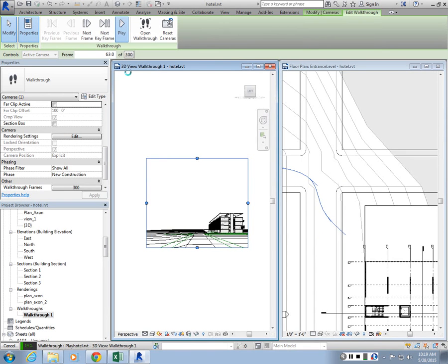No, I specified the path, and now I'm going to show you how you can also change the angle or the placement of the cameras in between. And what it's doing is basically interpolating. The spline specifies the movement of the location of the camera, and then you can specify custom target views at specific keyframes, and then they will be interpolated as the camera is moving, right? So if at a specific keyframe you want to look at the building at a specific angle, you can set that, and then the next one that you set, it will start turning towards that. So it's basically interpolating the location as well as the target of the camera.